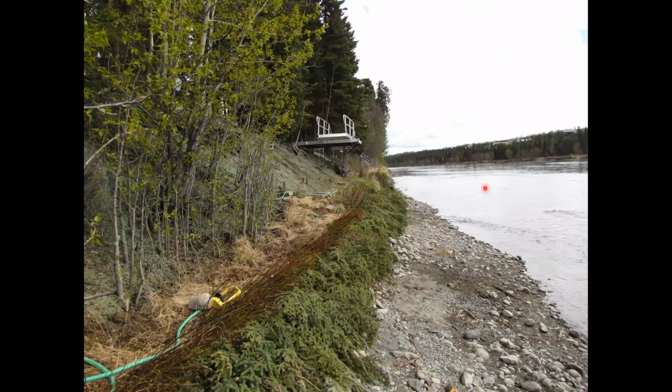So here's a photo from the Kenai. We're looking upriver. This landowner had bought the property and the previous landowner had done some bioengineering and it just stopped. And so this all eroded back here. So the new landowner decided they needed to do something, and an easy solution for us was to install trenched willows. There is a coir log here, however, you can't see it because we have placed cabled spruce trees in front of the coir log. The other thing to note is we do have vegetative mat, and there are a few other issues with the hill slope here. So we have planted potted alders and some hydroseed.